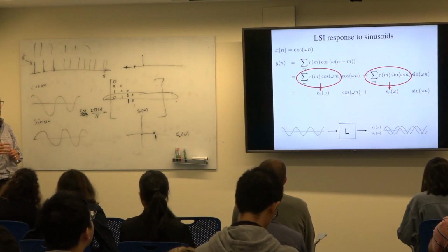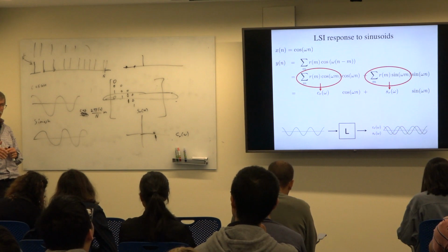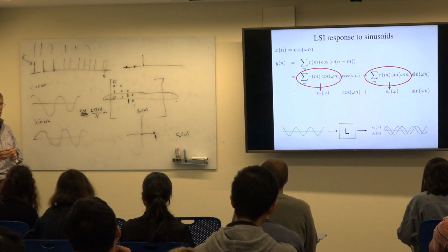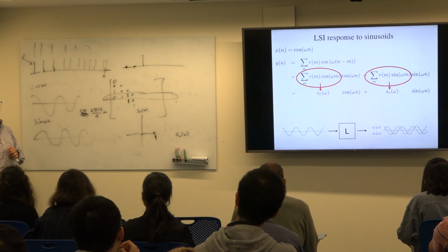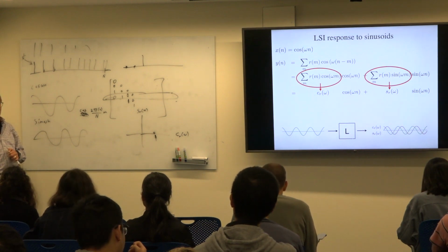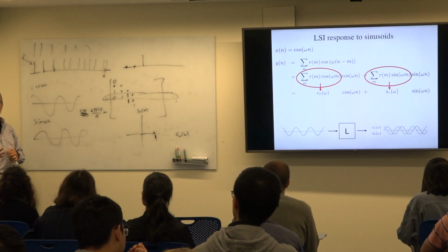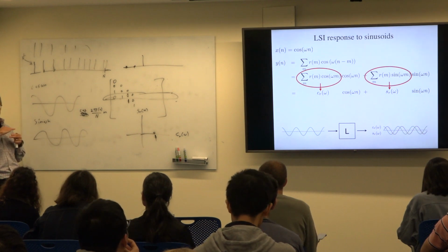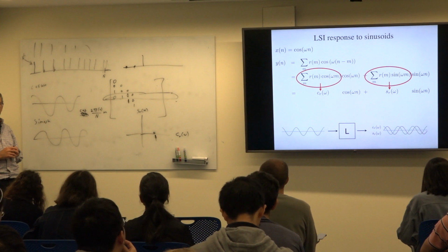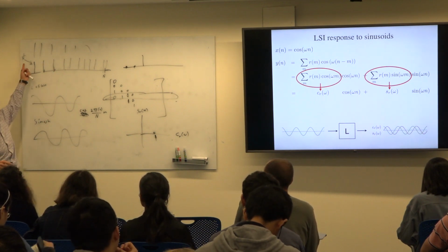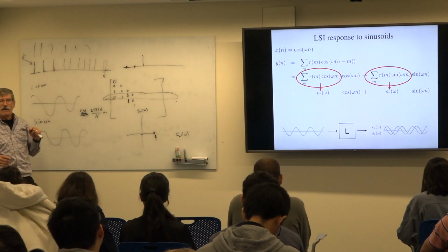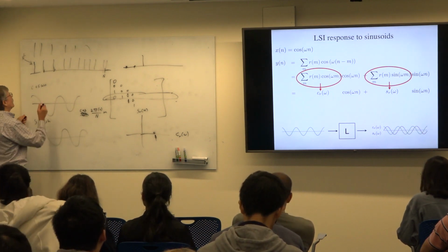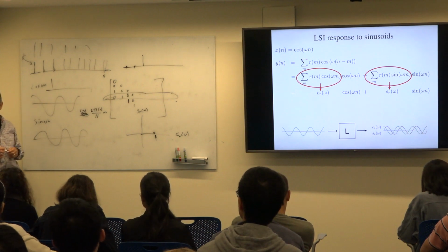Okay? So I've done some extremes about all frequencies get through or no frequencies get through. This idea of which frequencies get through, this filtering of my input signal by which frequencies get through and which don't, we need a little bit more math and a little more thinking about it until I'm ready to talk about that. But that's what you mean by the frequency description. You're saying my input has some fast wiggles, some slow wiggles, some very slow wiggles, and some no wiggling at all, some just constant input. And I say, which of those get through? And this one, this impulse response right here, deletes all modulations, all frequencies, and only lets frequency 0 get through. This one lets all frequencies get through.